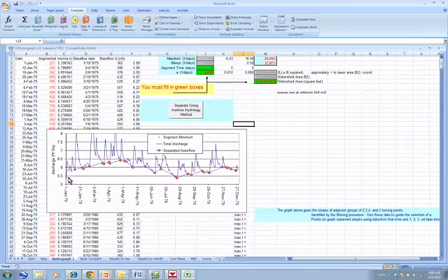And you see marked on here in pink, these are the minimum flows, in this case every 7 days. So we blocked off the data set into 7-day groups, and we took the minimum flow during those 7 days, and that's the pink points. And then we do a separation or a filtering using the method that's described by the Institute of Hydrology, and it gives these points here as base flow turning points.